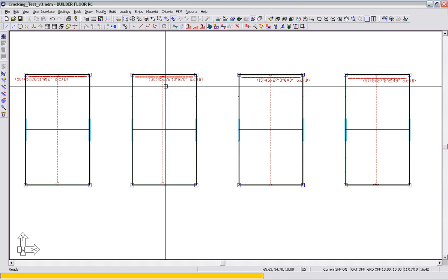So if you're trying to validate what happens when you increase the quantity of base reinforcing in a slab with respect to the crack deflection, the results may not differ because the program would be adding rebar just to satisfy strength and service demands. So in order to make the check, we recommend only setting up load combinations set to crack deflection.